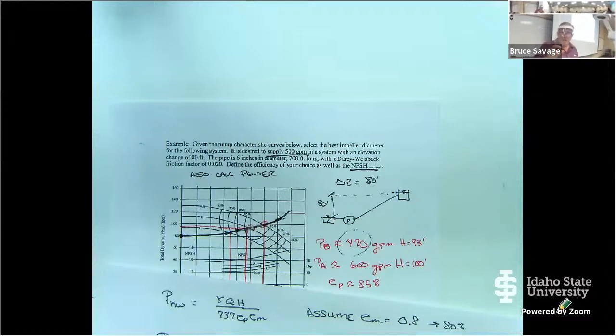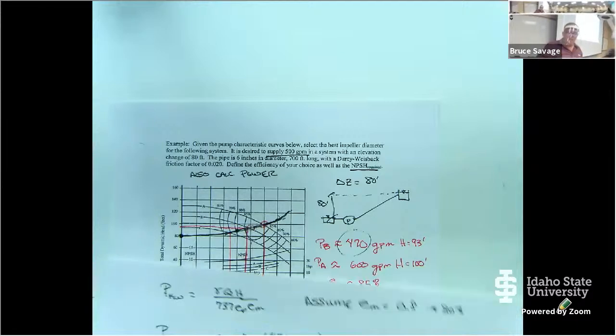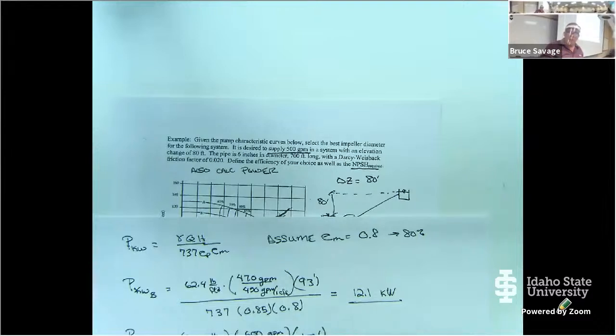And then look at our system. Does the 500 gallons have a safety factor built into it? We knew that sometimes we may need to go a little higher than that. If that safety factor is 1.2, well, I can take 6% out of that 20% over, and bring it down. But if I absolutely need 500 and it doesn't fit on my graph, I better go to the larger pump or find a different pump.